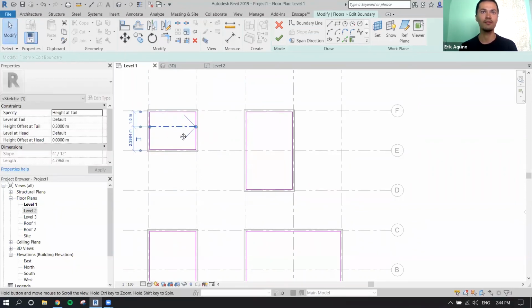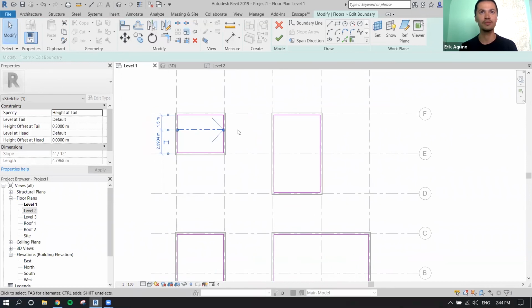Here, I will have my slope orient to the right. And there's a few options in which you could adjust the height of the slope, either by determining what the elevations are for each point, or through a ratio over here by selecting this drop down.